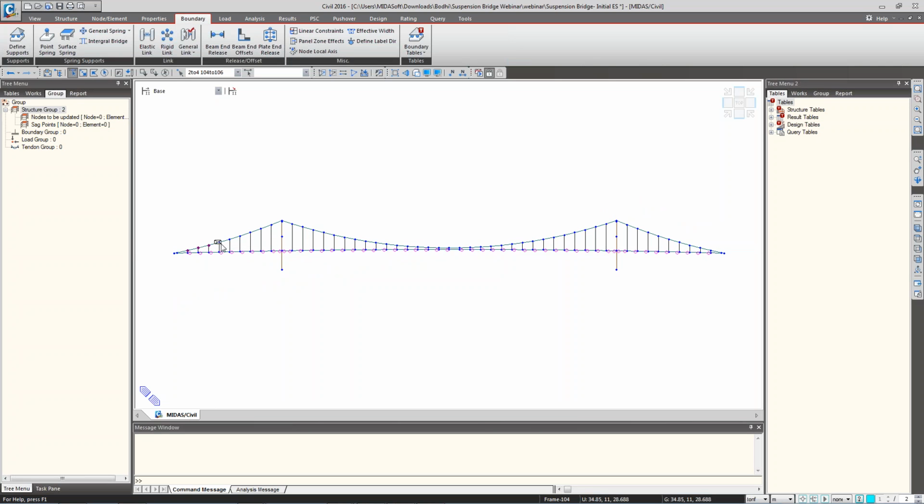If you are doing it manually, you just give some cable coordinate and the program will automatically update it. You can go about selecting each cable coordinate that is there, or I can simply type in all the cable coordinates that are required. So I can just type in 2 to 10, 12 to 42, 44 to 52, 104 to, sorry, 114 to 144, and 146 to 154. Once you select everything, it will select all the cable coordinates that are there.